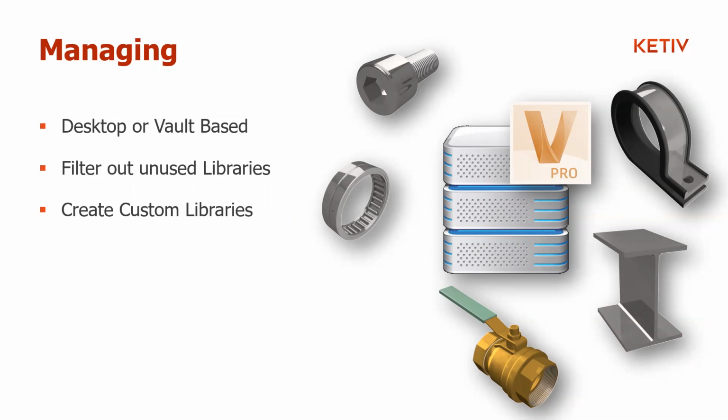This is a new take on this that you may or may not have heard of, but I recommend creating a production content center library and a test library. You want to isolate what you're doing and experiment, making modifications and customizing in your test library.